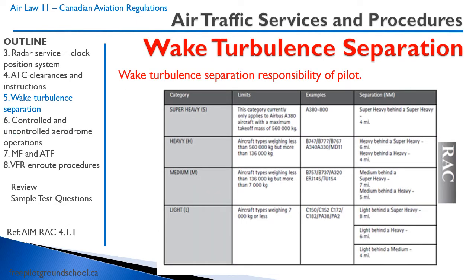In aircraft, especially large aircraft, we have something called wake turbulence, which we'll learn considerably more about during your flight operations lessons and your theory of flight lessons. These are caused by wingtip vortices. We can make a rough analogy that they are similar to the wake behind a boat, but they are most prevalent in heavy aircraft when they are taking off. They can very easily in a large aircraft flip another aircraft over. This has happened. A light aircraft takes off behind a medium or heavy aircraft and it just flips the plane right over. That plane crashes into the ground.